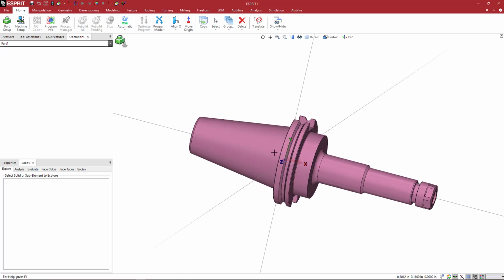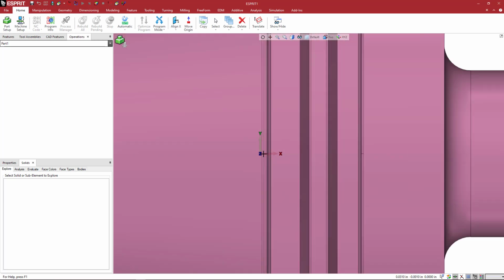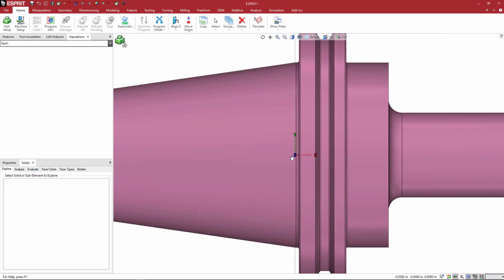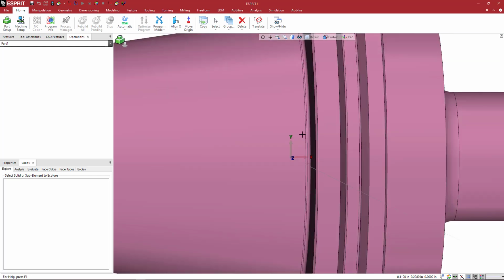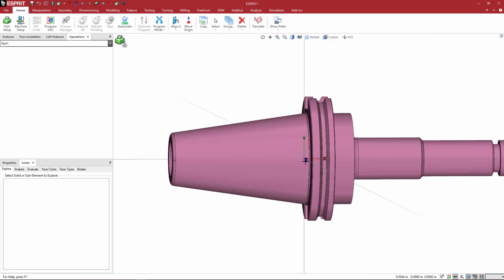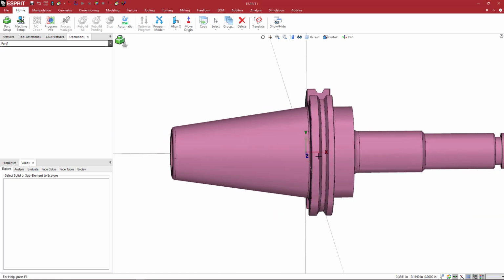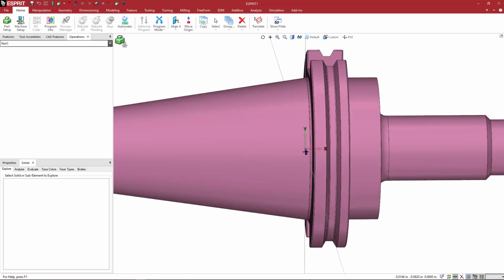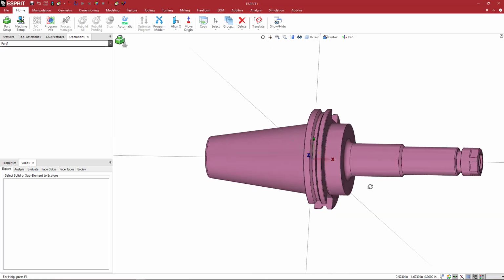So here we can see that it's oriented about the x-axis, and we want this oriented about the z. Additionally, if we look at the positioning, it looks like if I go to just a standard view here, I see that this is slightly off. I'm going to assume that this is probably where it needs to be on the machine. So when it's on dual contact, this is an SX holder for dual contact. So I'm going to assume that the location in terms of in space, that this is in the correct location. I'm just going to change the orientation of this particular holder.